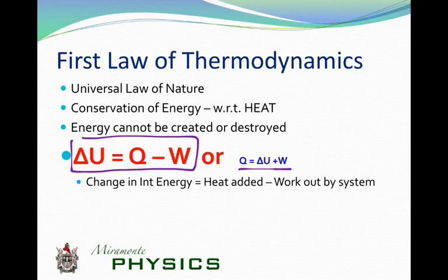This is exactly the same equation, just rewritten, but this is our bank analogy where you add heat and then you're going to change the internal energy or be able to spend that energy in doing work on your environment. So that's like your checking account. Okay. But delta U equals Q minus W. That's the typical way we write the first law of thermodynamics.